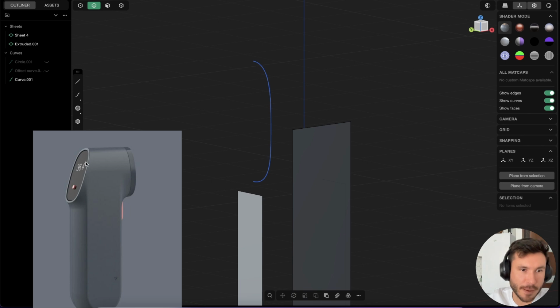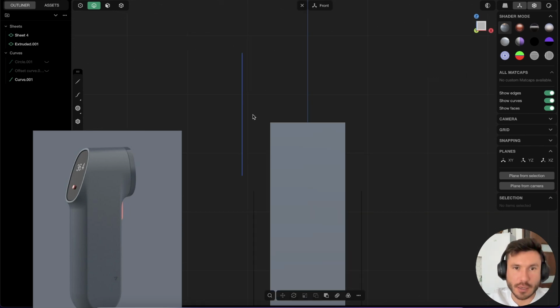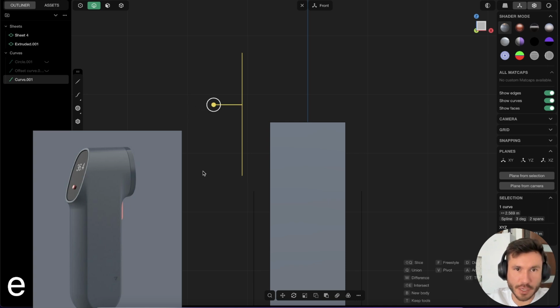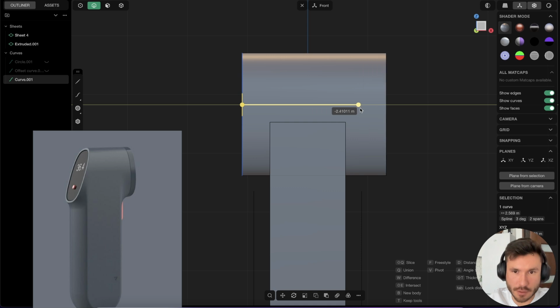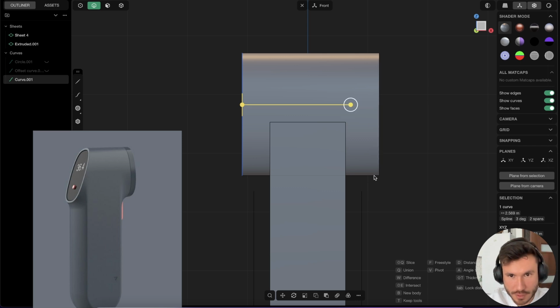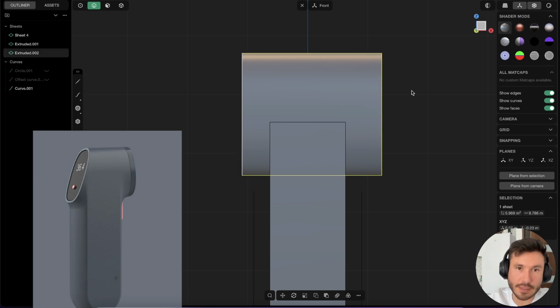And what we see here, we have an angle, and here it's straight. So the easiest thing is if you just select this curve here in the front view and press E for extrude, and you just extrude this till here will be this edge, right? So just give it a little bit of a distance, so we can then give it a nice curve, so something like that.